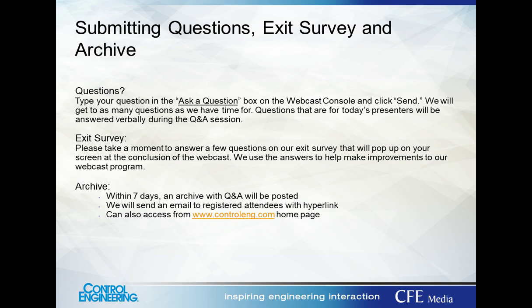So the problem is that error minimization is an aggressive criteria, and it leads to a lot of MV movement or fast MV movement and excessive overshoot and oscillation. In industrial process operation, these are the least desirable performance characteristics. It's much more important to get to set point at safe speed and with minimum overshoot and oscillation. So that's the good news, is I think industry's been learning that.